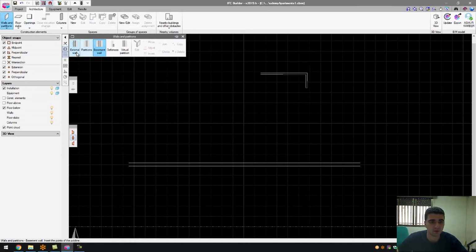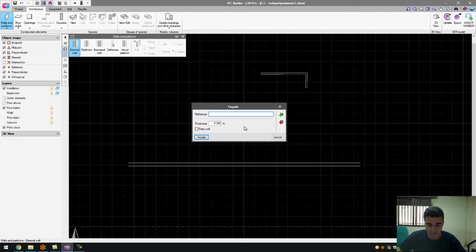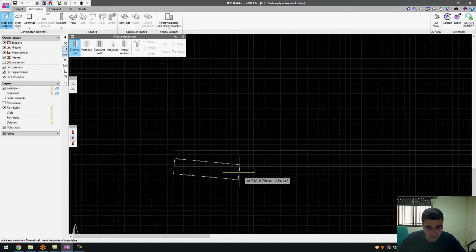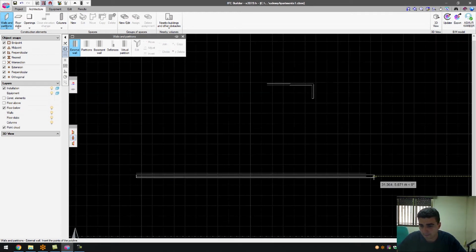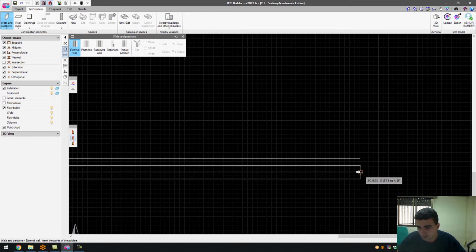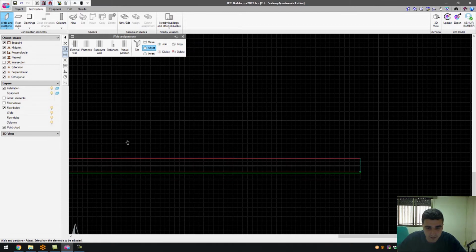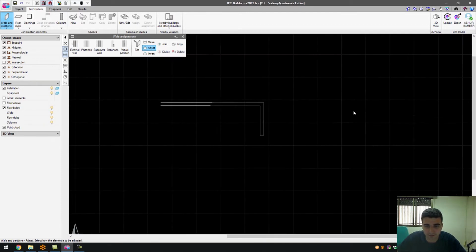Let's insert the external wall initially. So let's go to walls, external wall, insert. So let's call this basement external wall 01. My apologies. Basement external wall 1 with a thickness of 0.3 meters. Let's accept those changes and let's start adding it. As you can see, I've chosen the wrong configuration here, but what I can do is I can adjust, click it, and move it up, and perfect. It's now aligned.